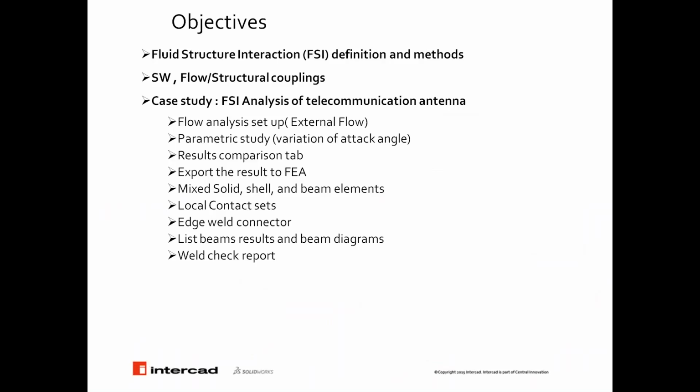Then we are going to focus on the SolidWorks fluid and structural coupling methods we have, explaining what the procedure looks like. We will continue our presentation with a case study. The model of a telecommunication antenna has been selected to do the FSI analysis. In this regard, we first start with the flow analysis setup as an external flow over the object.